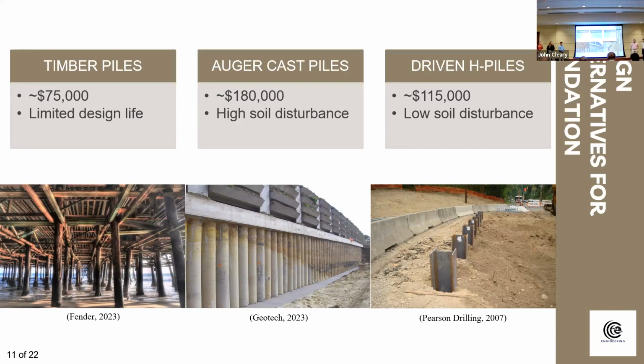Okay, so auger cast piles are constructed by going out there with a big auger and augering into the ground. It's either gonna be soil displacement, or a non-displacement pile because you're taking soil out and just pumping concrete and throwing your rebar in. So that is actually a lot less disturbance of the surrounding soil stratum.